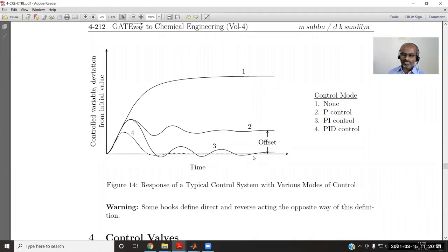And here we are now changing the load. In spite of any changes in the load, the system should remain at the initial steady state. Initial steady state is simply the 0 horizontal. This is the 0 level. Whereas with no control, the system is stabilizing at another value. That is a first order system. Now we are changing the input and it is now settling at a new value. That is a first order system.